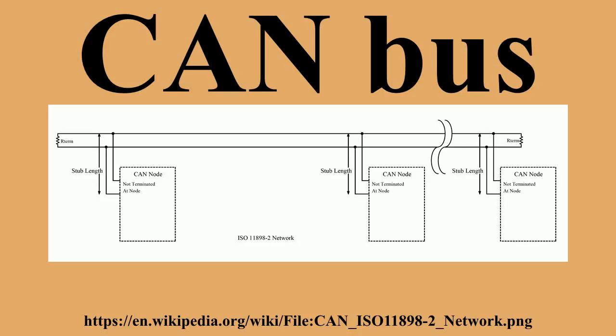ID allocation. Message IDs must be unique on a single CAN bus. Otherwise, two nodes would continue transmission beyond the end of the arbitration field, causing an error. In the early 1990s, the choice of IDs for messages was done simply on the basis of identifying the type of data and the sending node. However, as the ID is also used as the message priority, this led to poor real-time performance.